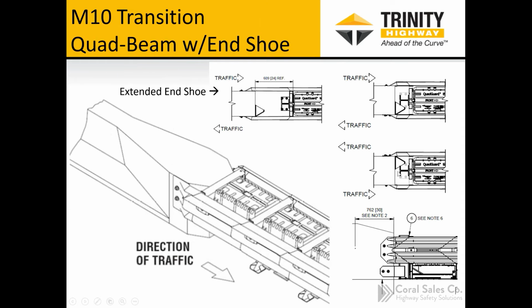If you're not able to taper the wall, and that's what we're showing here, it's a weldment that's attached to the concrete wall, and we call it a wheel deflector. So rather than taper the concrete barrier, we offer another option, which is called the wheel deflector, to ensure that the vehicle, as it hits into this square concrete wall, doesn't snag its wheel on that and get hung up and have extra force that is undesirable for the crash test, or the real life impact.